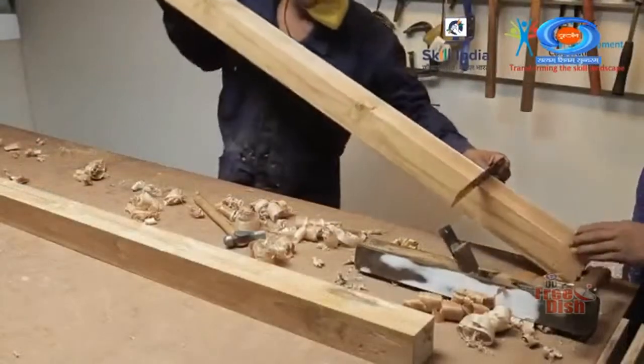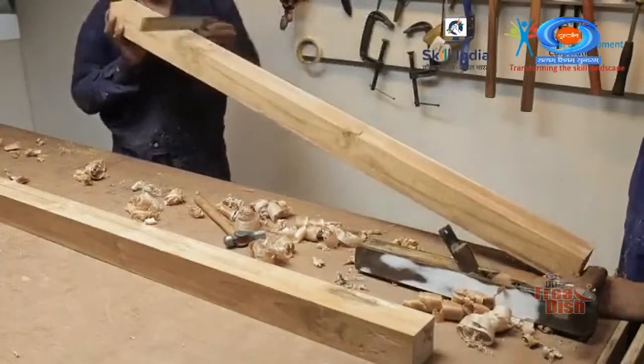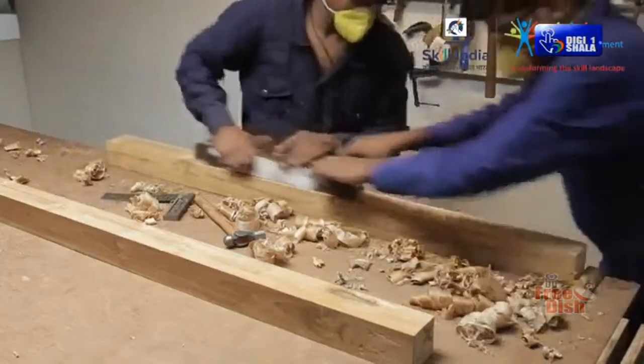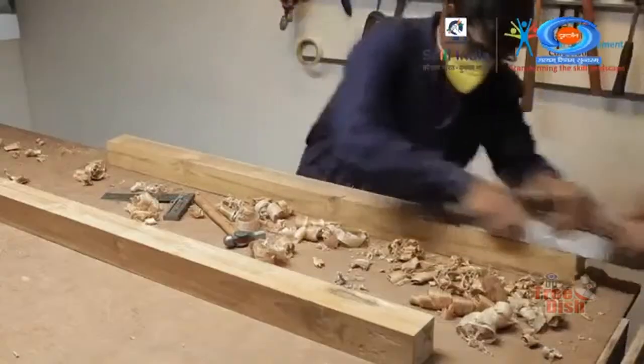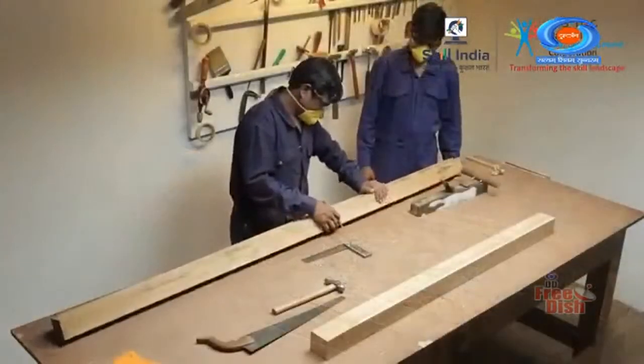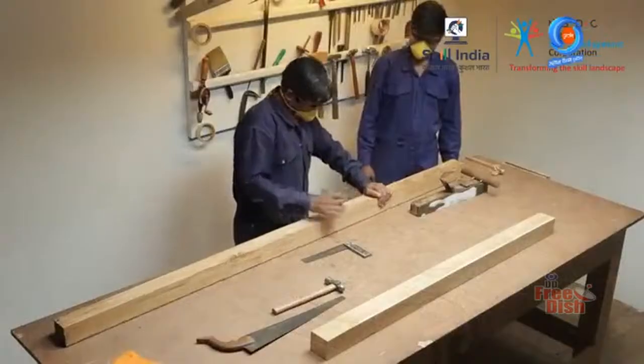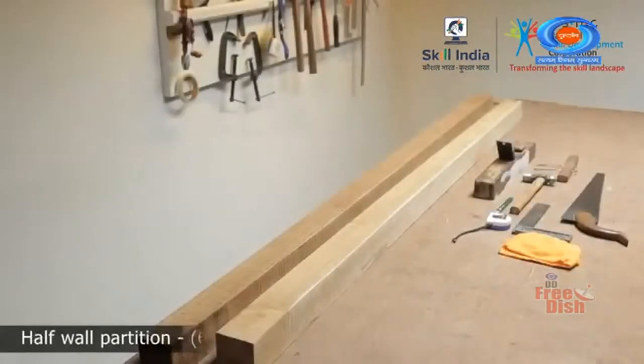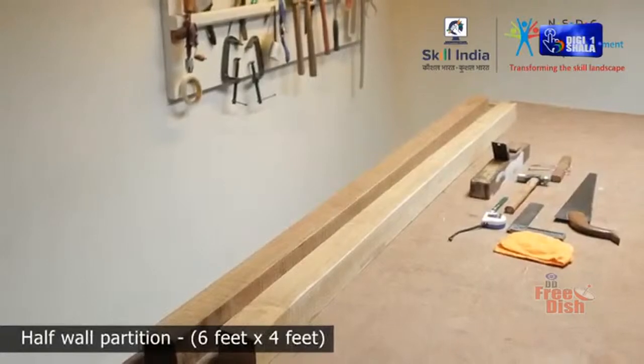Use a tri-square to check if the edges are cut square. If required, smoothen it further. Mark them as the face side and face edge. All other measurements must be taken from either face side or face edge. Here we are making a half wall partition of 6 feet by 4 feet.